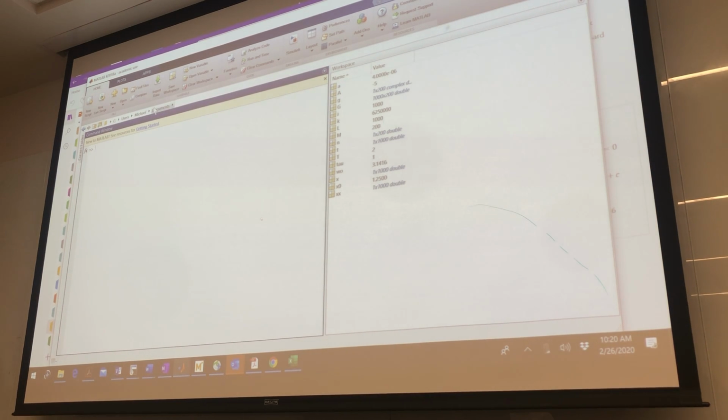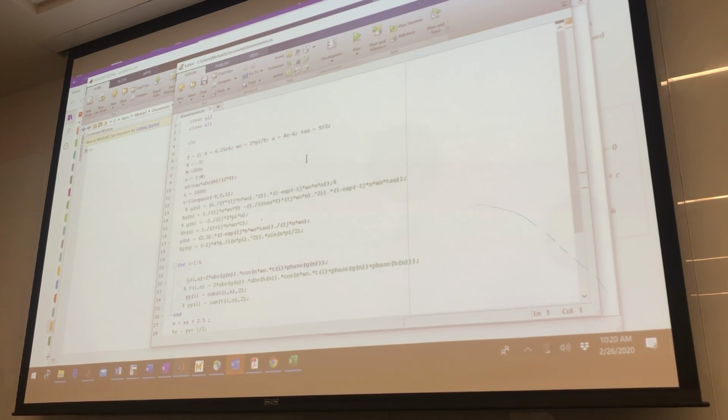So for mine, I have to open my file. And this is what I had. Now I'm going to add the part where I include the H transfer function. I call my transfer function H of n. You all see where I am, right there. I have it as 1. Now you see that dot after the 1? That's important because it means it's going to do element by element division, not matrix division. I'll talk more about that in a second.